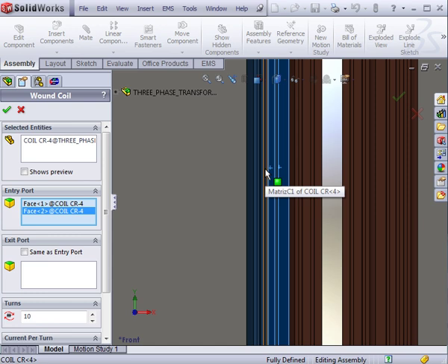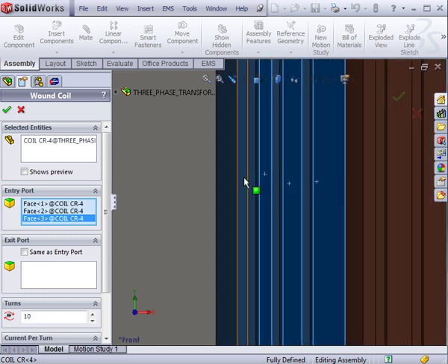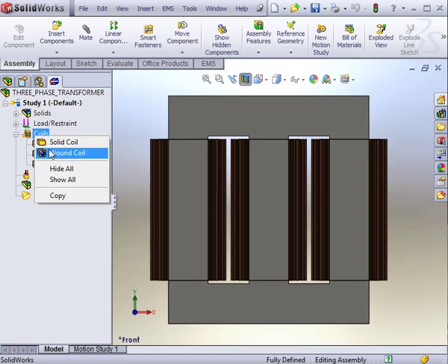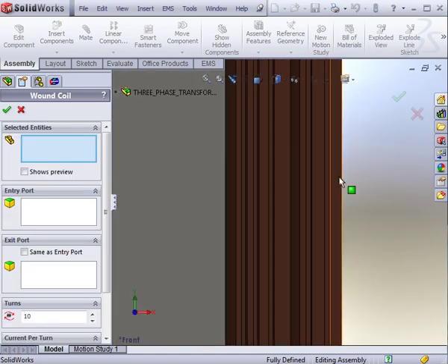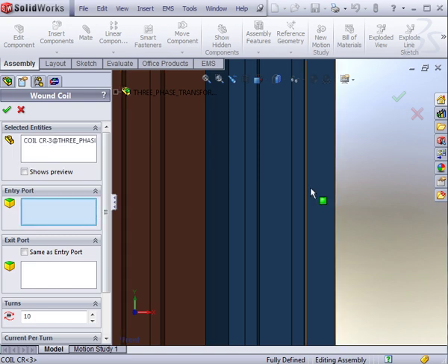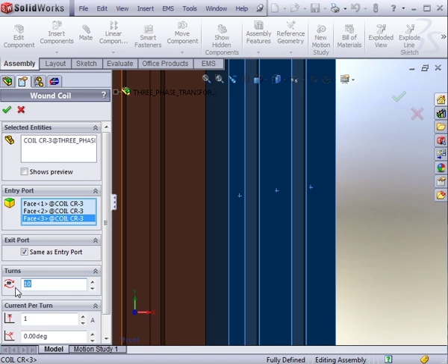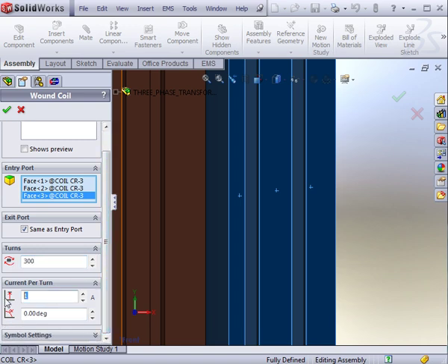For the inner coil on the left, while it shares the number of turns, the direction of the current, and the amplitude, its phase is 240 degrees. All outer coils share the same properties. They all enter from the right counterclockwise and have 300 turns with 0 current.